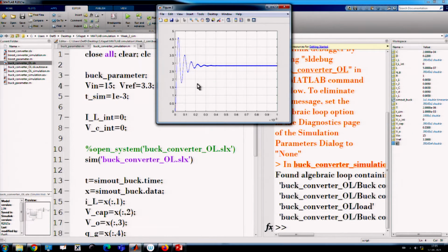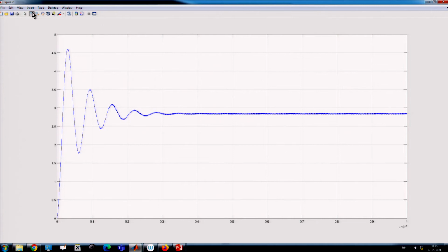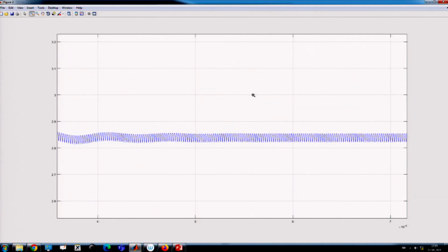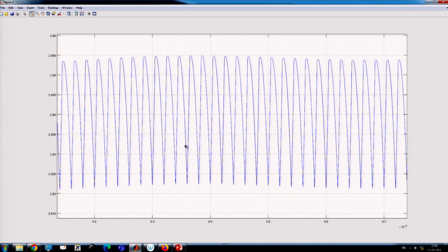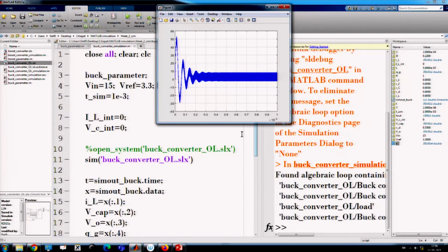Now the output voltage actually gets shifted, but it is not exactly 3.3 because we have discussed that the output voltage difference is due to the drop, because we have considered the non-ideal resistor, inductor, capacitor, all this. So, inductor DCR drop, diode drop, then diode resistance drop, many things will contribute to this mismatch in the output voltage. Okay. But yeah, at least we can run.